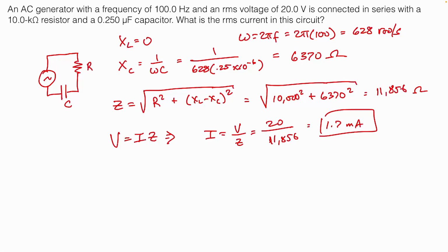I always start with just finding reactances. I know I'm going to turn everything into a resistor, so just turn everything into a resistor. And then I calculate my impedance. They might not even be asking for it, but if I'm going to have to calculate a current or anything else, I'm probably going to have to use the impedance, right? And so on and so forth.